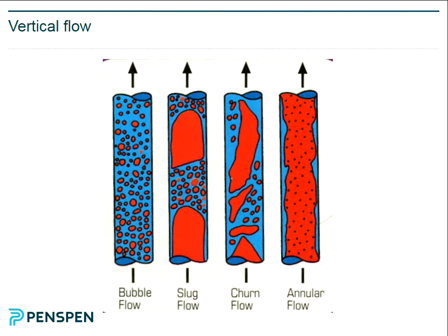And this is a special case. This is where you actually intentionally make two-phase flow to help you. And this is a gas lift well. So this is the annulus. This is the production tubing. These are gas lift side pocket mandrels here. This is a sealing collar. That's not the right term. I can't remember what it's called. So the idea is that this is the reservoir down here. These are the